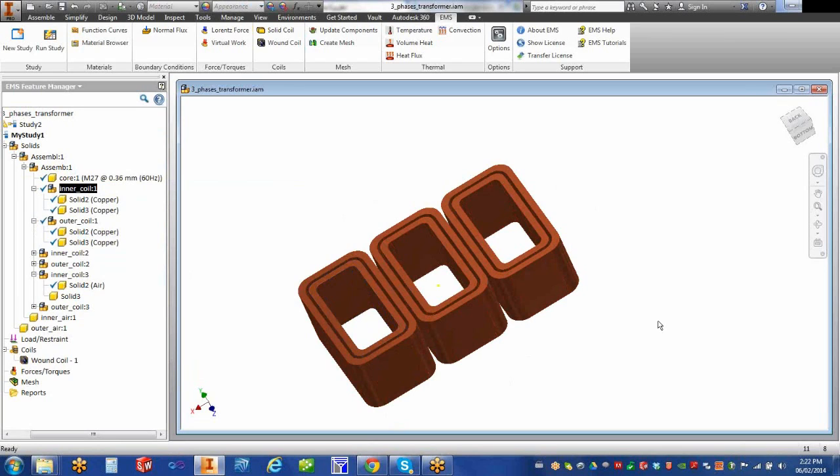And the answer is you don't need to do that, because if you put individual wires, they're going to complicate the geometry and the meshing without benefiting anything. Why? Because by saying this is the volume and specifying the number of turns, the simulator knows internally it's going to take care of that for you. So there is no need to model individual wires. And if you want, yes, EMS can handle that, except it will take a longer time to mesh and solve. All right.